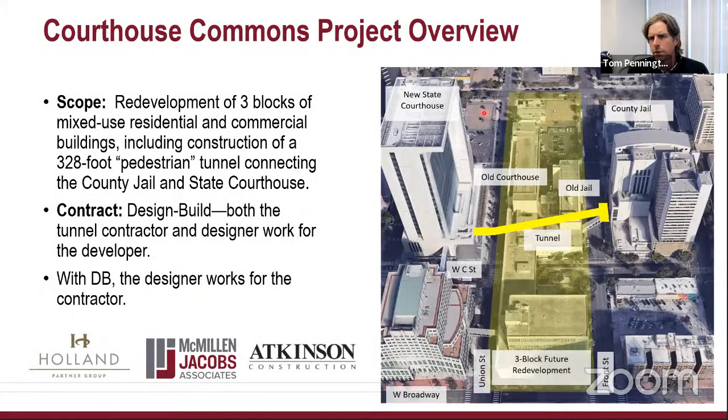So here's another view. You can see the various structures next to the alignment, and the tunnel basically in yellow here passing beneath what's termed the old jail and the old courthouse structure. Those structures were actually in use when the tunnel was being mined, and we had extensive instrumentation to monitor the effects of the excavation.